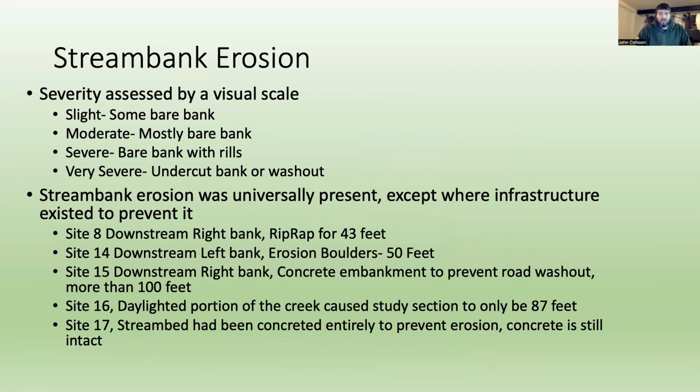This one was assessed purely by a visual assessment. So did we have bare bank? If there was some bare bank, it was slight. If it was mostly bare bank, it was moderate. If there was bare bank with rills, so rills are like the predecessor to gullies.